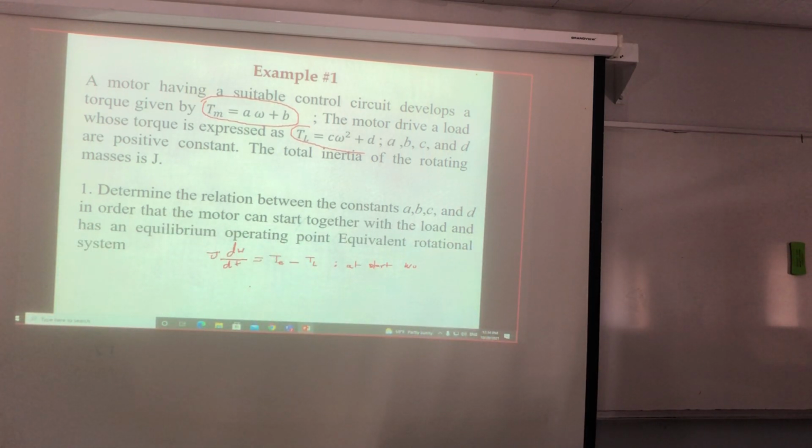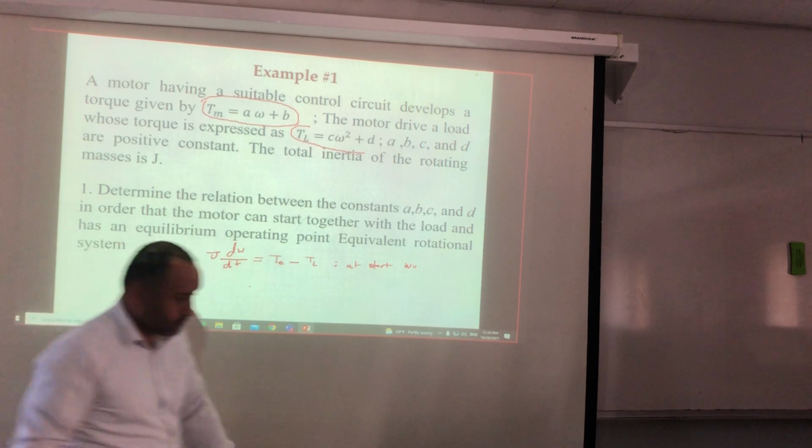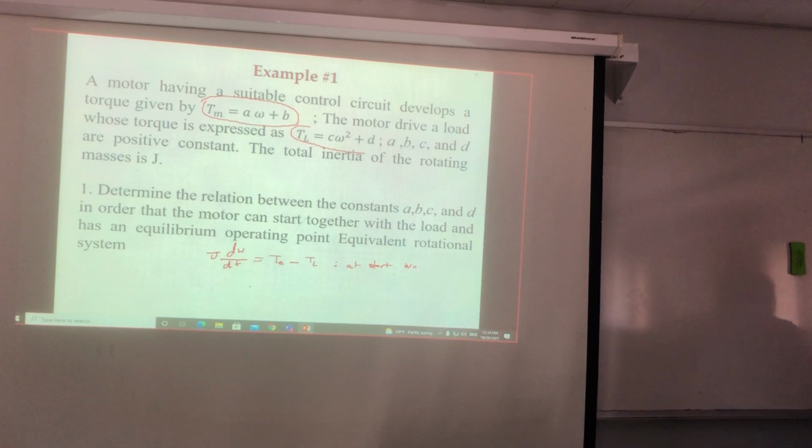If they are equal, they will stay there. At the operating point, they will be equal. But while I'm accelerating, they will never be equal, otherwise I cannot move. So this states that Te is greater than TL.